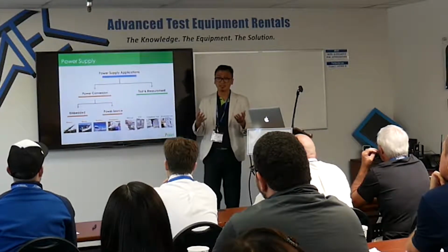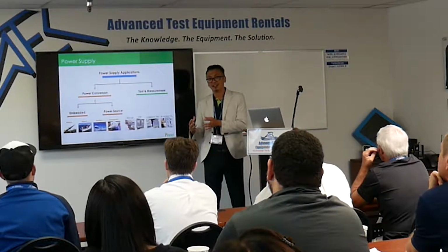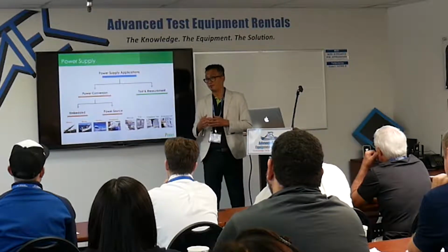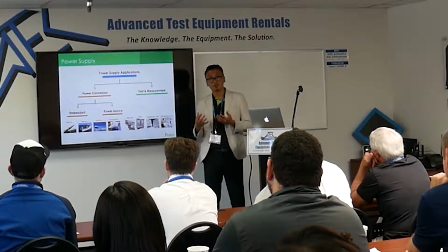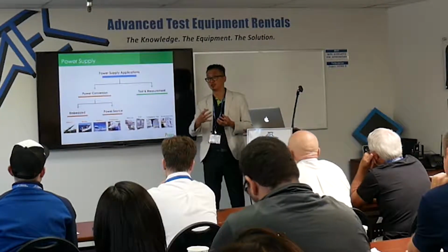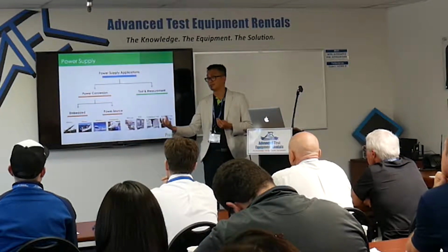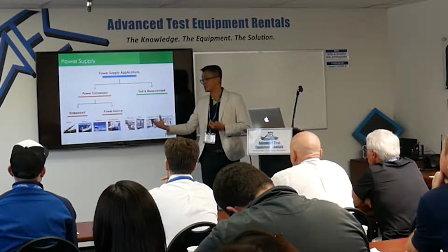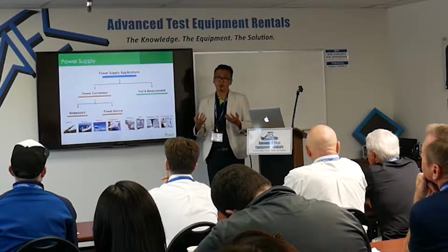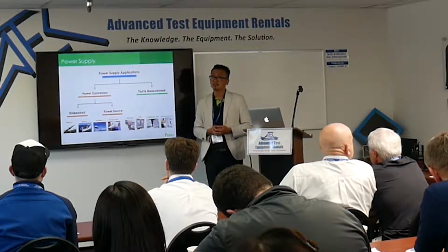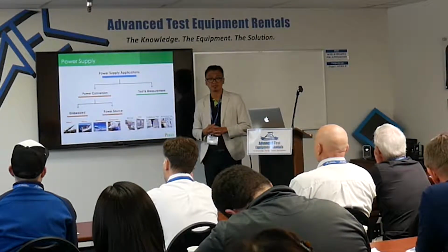The reason we need to test the upper and lower bounds is that the product's performance can be very different there. You have to make sure your product works well in different power conditions when you ship it all around the world or to different countries. In your test lab, you cannot guarantee it's always 220. Sometimes 208 may drop down to 190, or go up to 240. You want to make sure your product works well in that kind of circumstance.